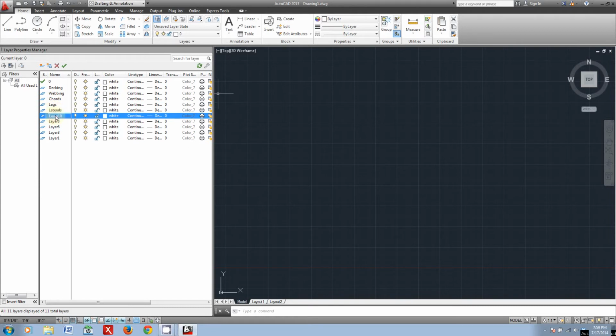How about a couple things that aren't bridge related? What about load points? Points where we'll be applying load in SAP, or maybe even deflection points. That can be useful as well. Now we also might want to include something like boxes. And this will be the bounding boxes that will restrict member size. That's the 3 foot by 6 foot by 3 foot by 6 inch by 4 inch box.